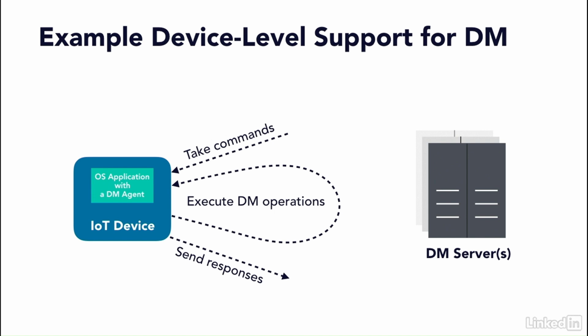For example, the device-level support for remote provisioning and configuration would require the device to save data received from the remote servers to its own storage and do some possible encryption operations on the data. A more device-dependent functionality is software update. Software update, including firmware update, is a useful and common functionality, but we'll need to use the device software and hardware platform features to implement it.